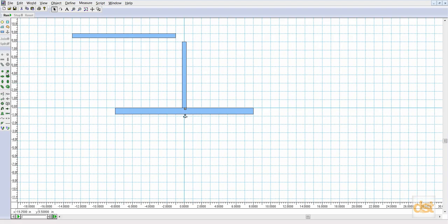If the bodies are already in position, for example, if these two bodies were positioned right at that location, I could simply click on the constraint and then click right here where I want to put that pin. And then the bodies are already assembled at that location. However, if I have a body that's off in space somewhere, and I want to join them at a particular location, and it might not be easy enough to use the grid or body snap tools to get the body into position correctly, I can use these element tools.